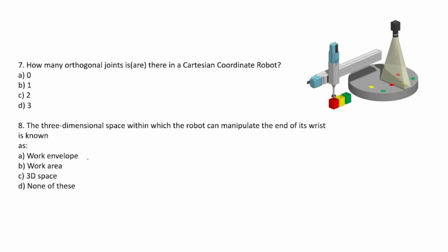Okay, now if we talk about robot body and arm configurations, there are basically five common body and arm configurations for industrial robots. One is the articulated robot, another is the polar configuration, then the selective compliance arm for robotic assembly, which we call SCARA as well, and then Cartesian coordinate robots and delta robots.